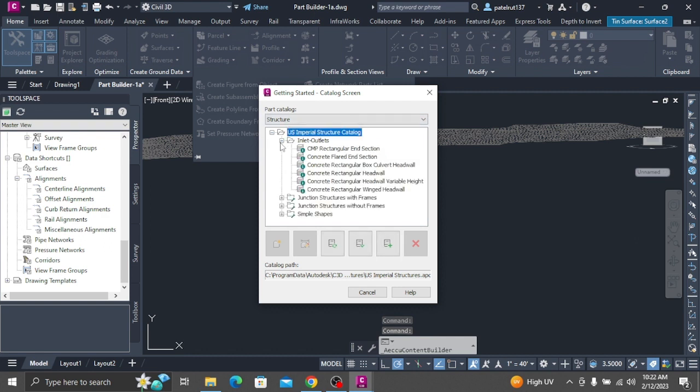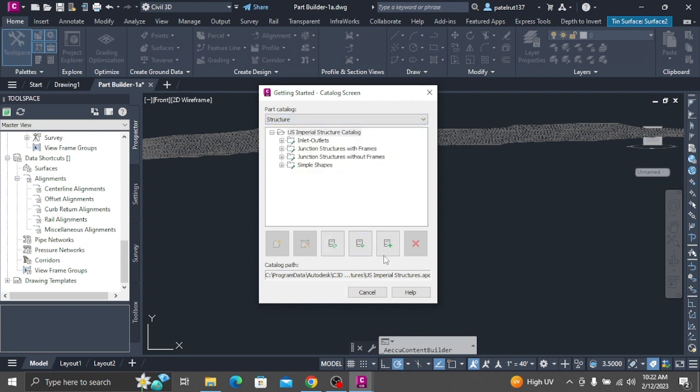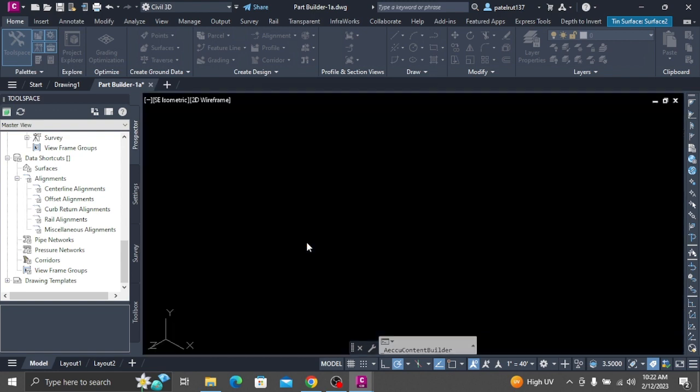Expand Model Parameters, right-click Model Parameters, and then click Edit. The Model Parameters dialog box is displayed. Click Len B2, then click Calculator. Click Variable, then select Len B1. Enter +1 after Len B1 and then click OK, then Close.